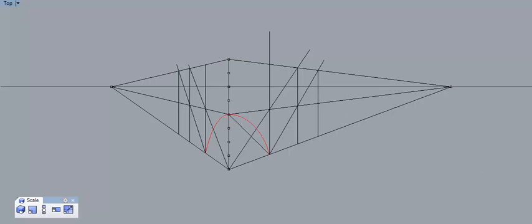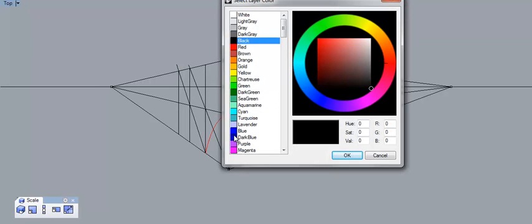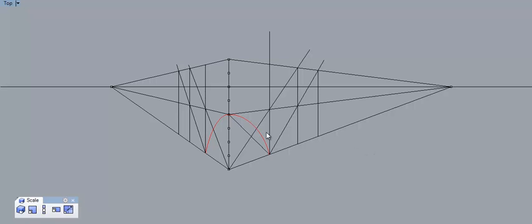Alright, so now at this point, I'm going to go ahead and generate a new layer, and I'm going to call this the ground. And I'm going to do that in blue so we can actually see this here. And this is akin to you utilizing multiple layers of trace. So what I can do is I set that to the active color that I'm going to draw with. I'm going to go ahead and project that 12 feet back, all the way back there. I'm going to go ahead and project this 12 feet back. And where those two things intersect, we now have a 12 foot by 12 foot square, or 144 square feet.